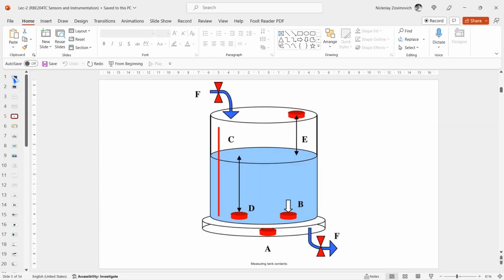This design process is illustrated by an example of a measurement of just a single static quantity: the amount of fluid in a container. For instance, we have a drink dispenser. Okay? The first question to be answered is, in what unit should the amount be expressed, volume or mass? This might influence the final selection of the sensor. So, this figure shows various measurement principles in a schematic way.